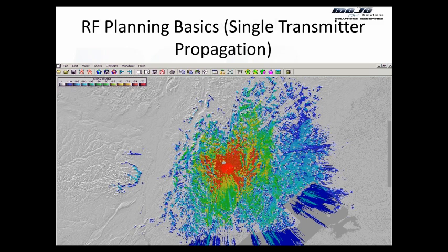The propagation model is predicting signal at different distances. The farther you move, the weaker the signal goes. How do you know? There is a legend on the left. It says blue is -10, so it's going in the ranges of -10. If we are closest to the site, you see a very good signal of -70 and -74 dBm. For you guys who are working in the RF field, you have a very good understanding. We always talk about the signal in minus because dBm is a logarithmic scale.